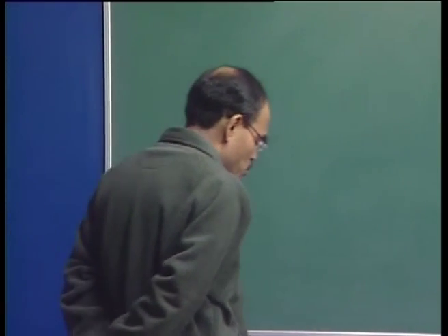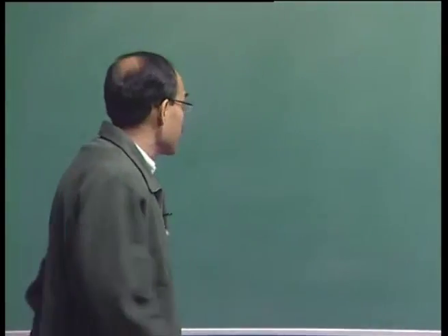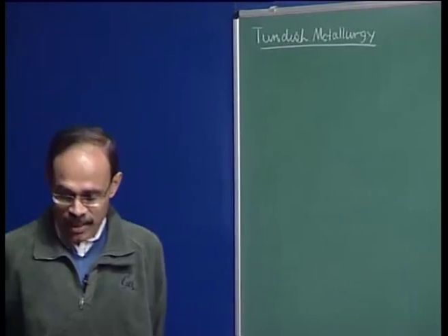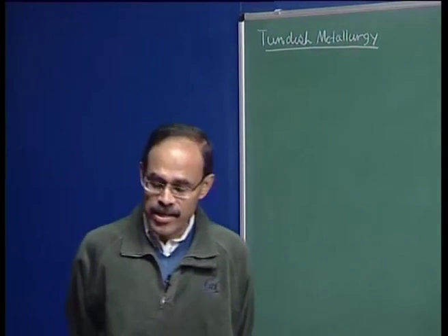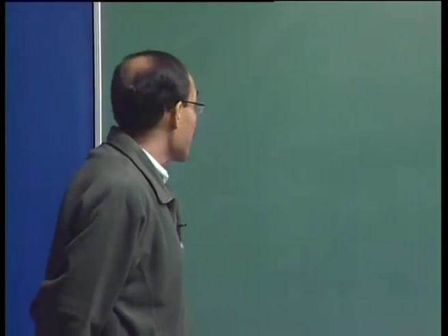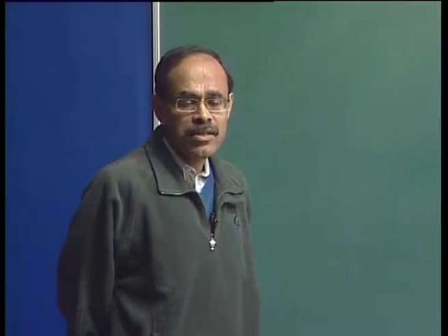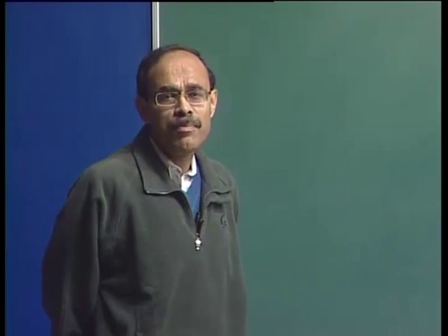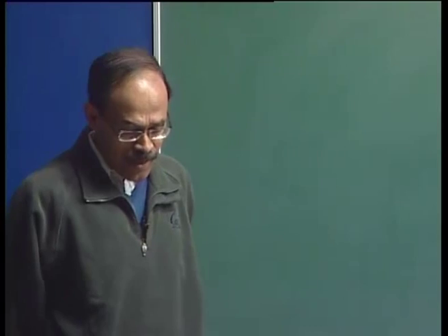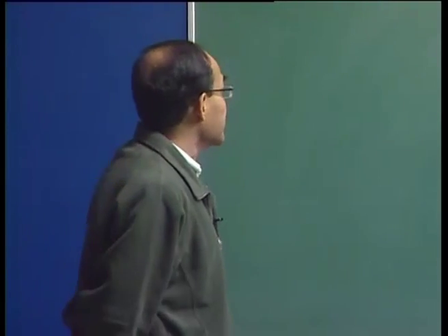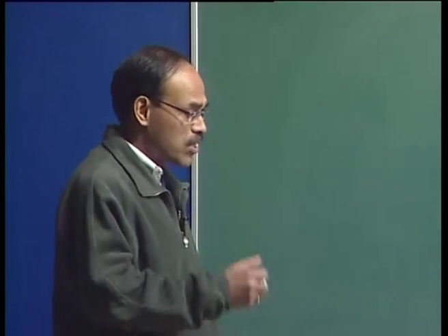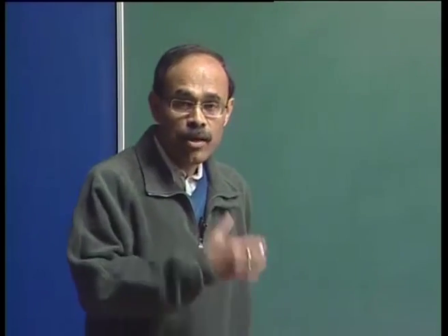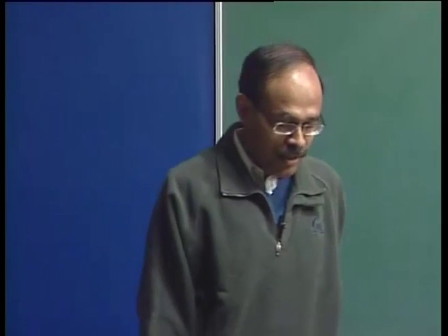Okay, when I was a student some 35 years back, we had nothing on tundish metallurgy. Actually, tundish metallurgy was not developed then, although continuous casting had made inroads in the area of steel making. But today, tundish has, as I have mentioned already, occupied a preeminent position in the steel making circuitry. And this is because of the simple fact that in tundish we can overwhelmingly control the characteristics of steel in terms of its inclusion, in terms of its composition and temperature, and thereby produce the right kind of cast products